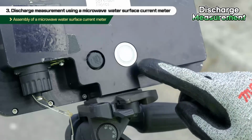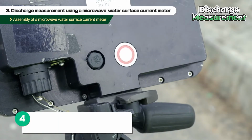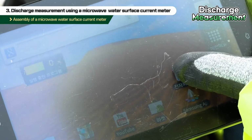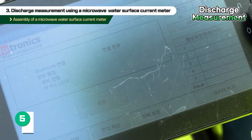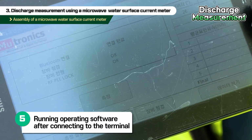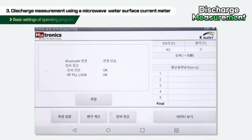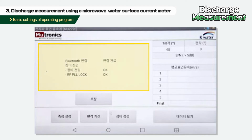After installing the device, press the power button on the back of the main body. Connect the power of the portable user terminal and click the icon of the microwave water surface current meter to run the operating software. By running the operating software on the beginning screen, confirm that the software automatically checks the wireless connection status and the status of the current meter body. The on-site worker should check to make sure the meter is connected normally.